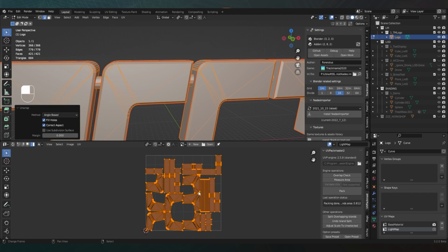And there's one thing that I discovered some months ago that is actually quite useful, and I think I'm not the only one that uses that. For light maps, always make sure to use your UV space that you have wisely, so the entire box. And currently we have a proper UV layout, there's no problem. But we could use it even more efficiently, because the more space you use that you have, the better your result will look.